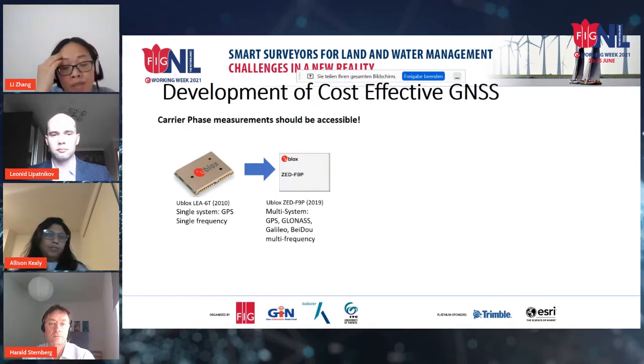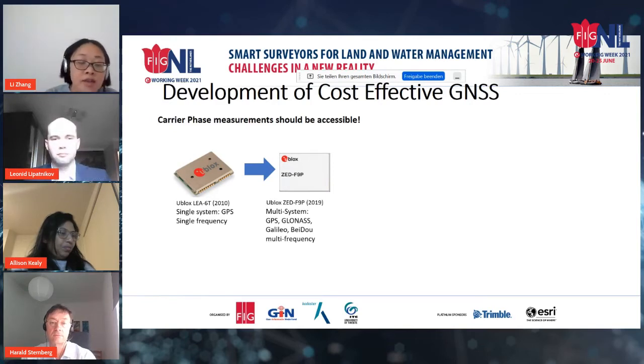And as I started my PhD, there were already several so-called low-cost GPS receivers available on which the carrier phase measurements are accessible. One of the famous providers is u-blox, and they cost only a couple of €100, and they can get millimeter to centimeter level accuracy for short baseline measurement. That means you can actually use them for deformation monitoring of small objects.